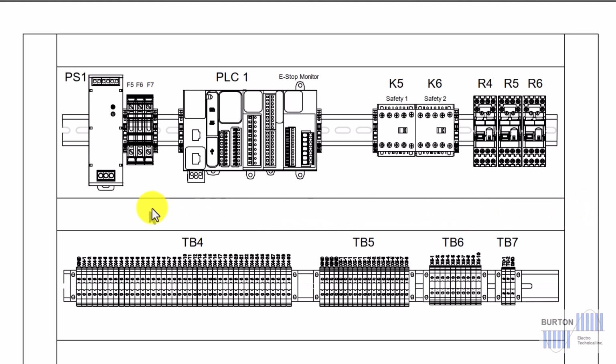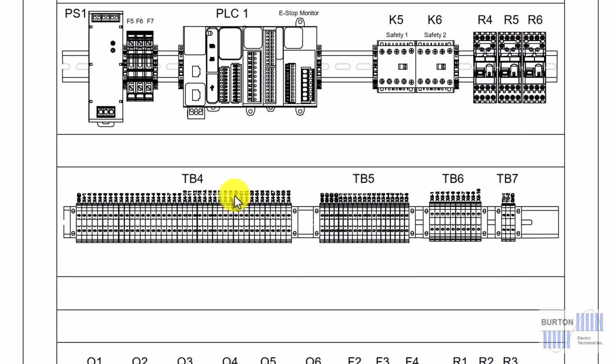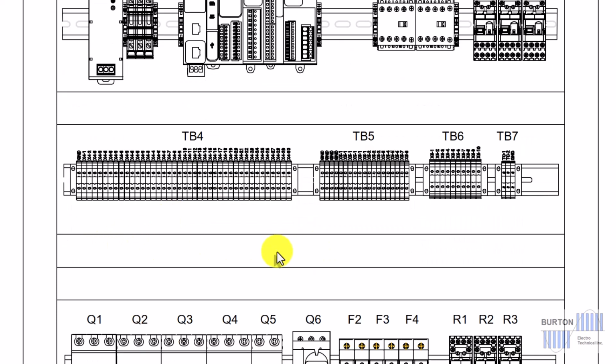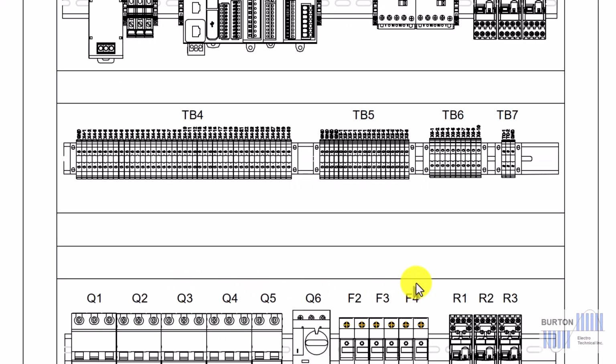And you'll notice that we have different compartments with duct above, in this case above what's called the PLC and below the PLC. All right, so we have our ducting. There are 2 rows of duct in the location of my mouse. The row above we use for the 24 volt power for control, and the duct below is used for power wiring for all of these breakers and fuses.